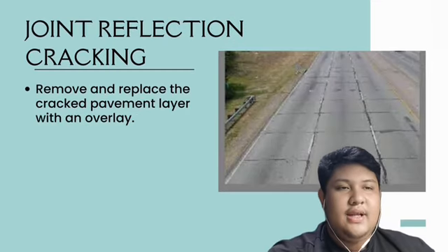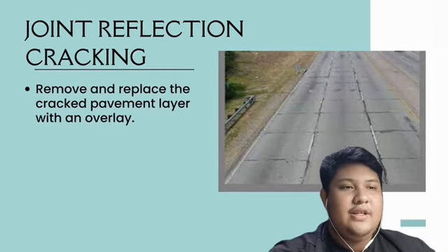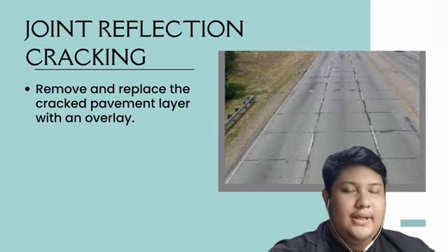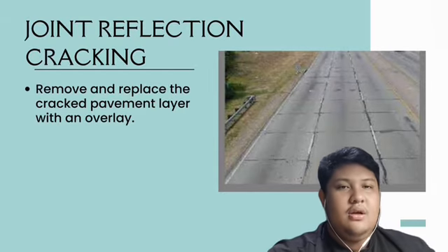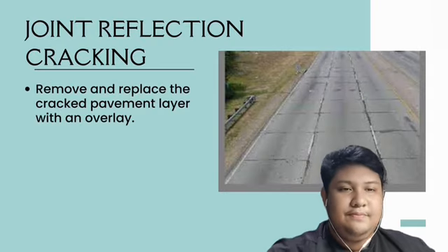Next, joint reflection cracking. We need to remove and replace the cracked pavement layer with an overlay. Thank you. I will leave it to the next presenter.